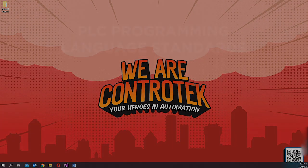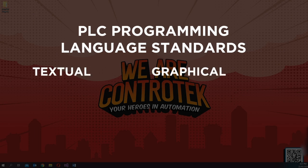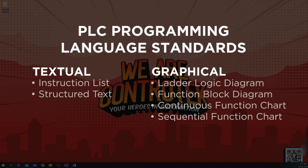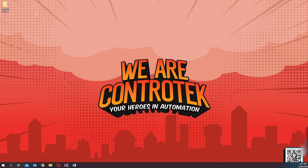Okay, now let's proceed with the discussion on the programming languages. Part 3 of the IEC 61131 standard deals with the 2 textual and 4 graphical PLC languages, which are instruction list, structured text, ladder diagram, function block diagram, continuous function chart, and sequential function chart. I will focus more on the structured text programming language, but I will be giving a brief definition of other programming languages and show you the basics on how some of them are implemented on TwinCAT 3.